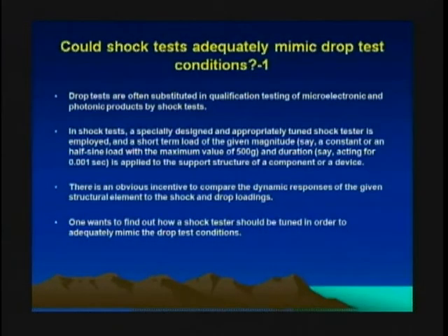In a shock test, a specially designed and appropriately tuned shock tester is employed. A short-term load of a given magnitude, say a constant or a half-sine load with a maximum value of 500 Gs and a duration, say, of 1 millisecond, is applied to the support structure of a component or device.